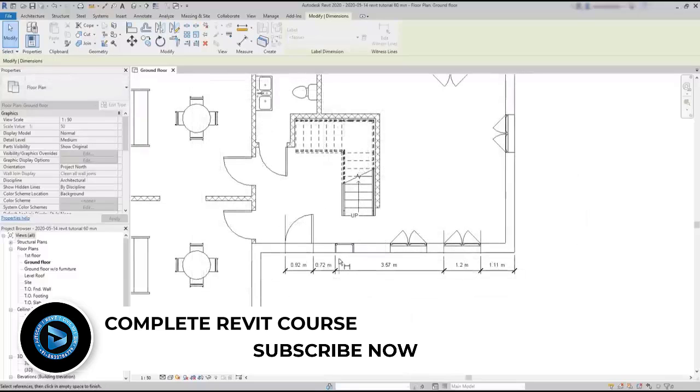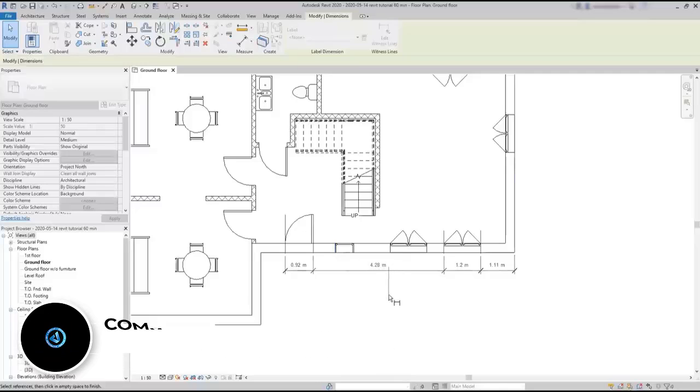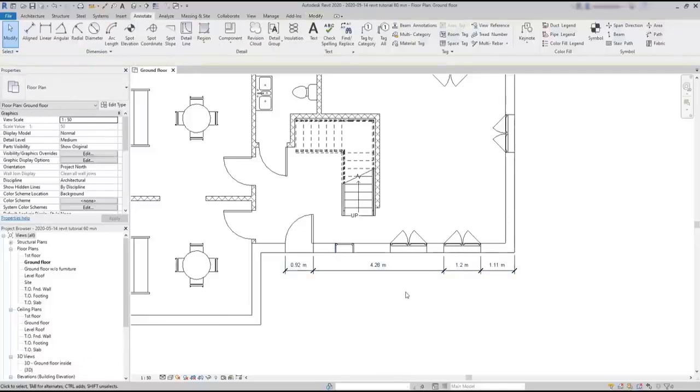Or even remove a witness line if I click on an existing one. At the end, click on an empty place to confirm the changes. And don't press Escape because it will cancel what you were doing.